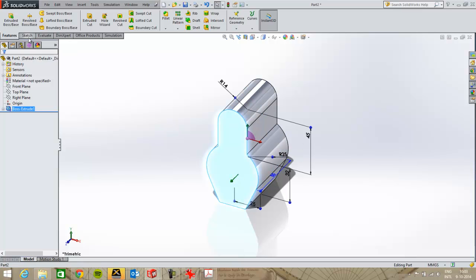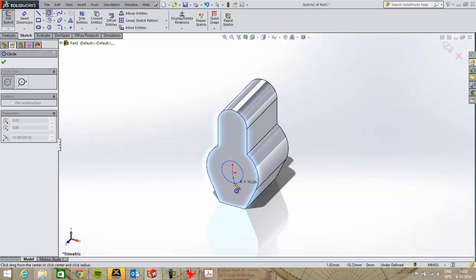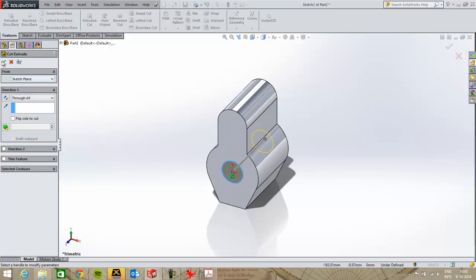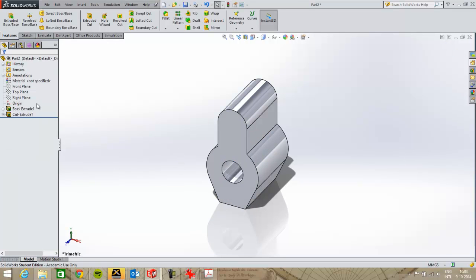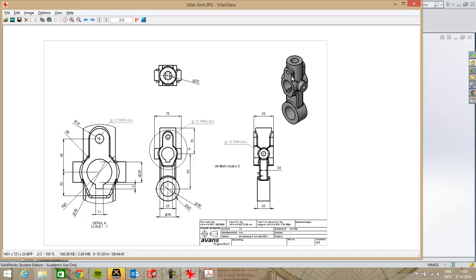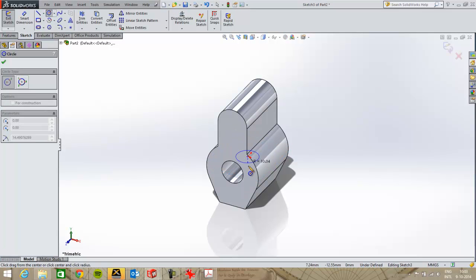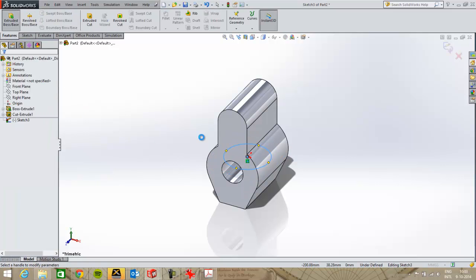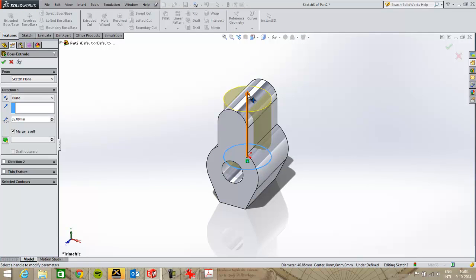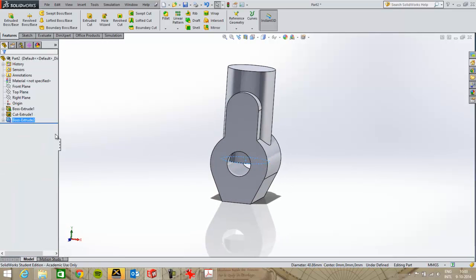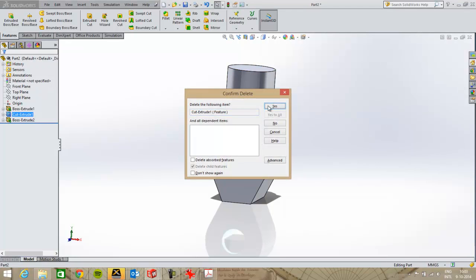Another thing to notice is that I don't draw the holes in this yet. I can show you what happens if I do that. Then I'll have a problem later on. So I'm modeling the holes, whereas actually I shouldn't. So through all. Now you see what happens if I want to draw on the top plane. Here I want to draw this circle over here, and I'll draw it on the top plane, sketch a circle. It's convenient to have the center over there, so you always know where to start your sketch. And now you see my problem. If I already enter the holes in the beginning, then you see it's filled again. So don't put these cut extrudes just yet. First add all your material, and then later on you start entering your cut extrudes.